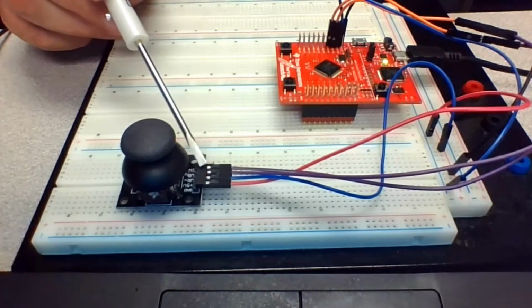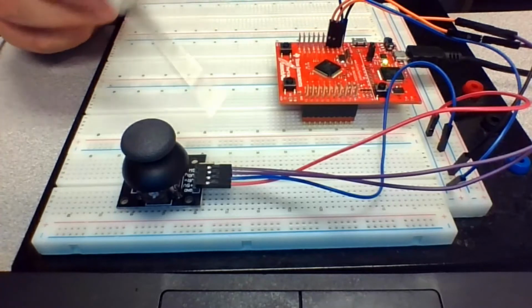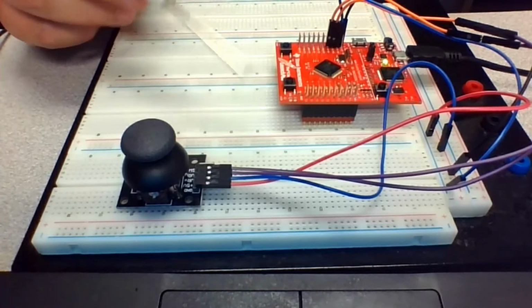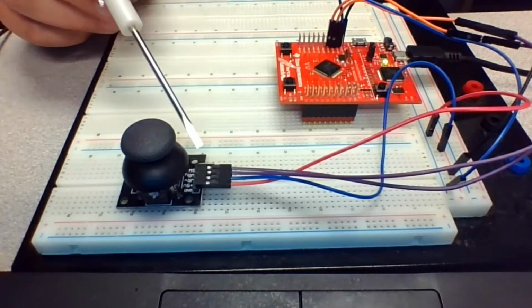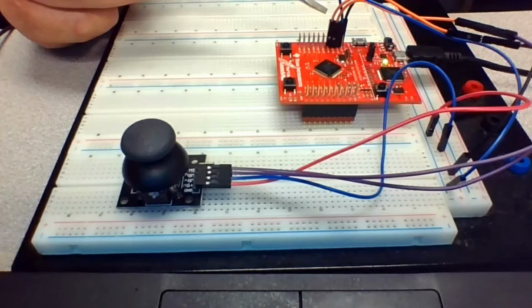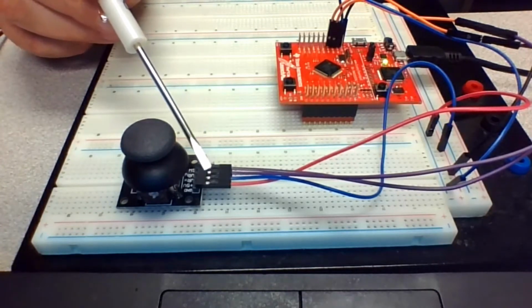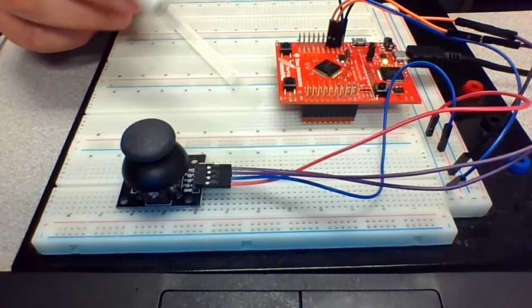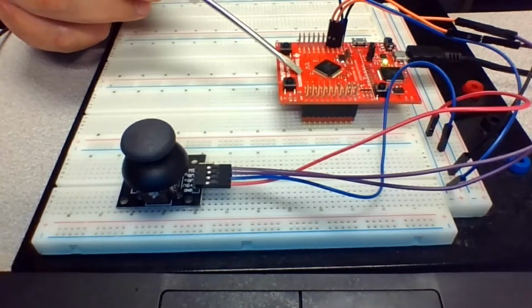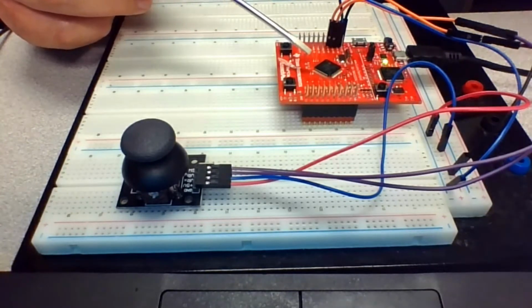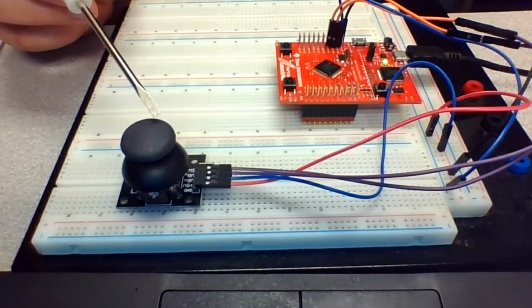The x-axis pin connects to one of the pins on your launchpad. We connect the x-axis pin to PD0, port D pin 0, and the y-axis to PD1. So this will be the whole story. Whenever you connect these x-axis and y-axis values to PD0 and PD1, you use the analog to digital converter in the microcontroller, and you are able to convert the values that you got from these two potentiometers.